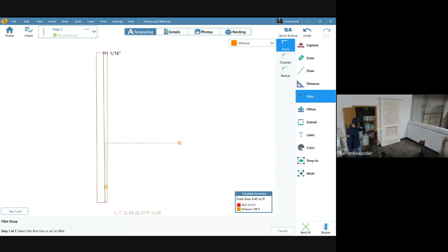With this new Leica, the L6G, this one's projecting all three lasers out here. So I can create level and plumb and the plane, and check the squareness of the face and what I create in my offset all in one laser setup when using something like this, right? So very powerful. Awesome lasers.